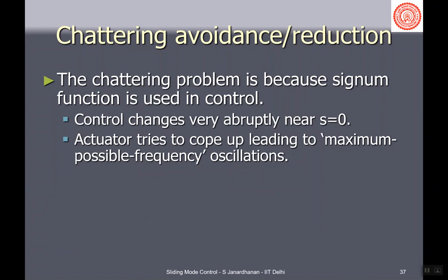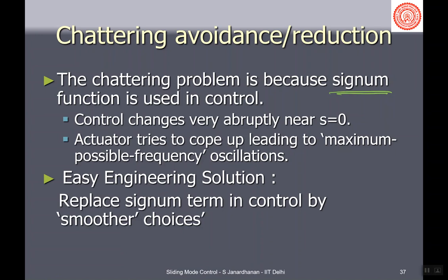Not really good. And the reason that chattering even exists is because you are using this signum term, and the control changes very abruptly across this. And what can be the solution? Don't use the signum term. Use smoother functions where there is no abrupt change.